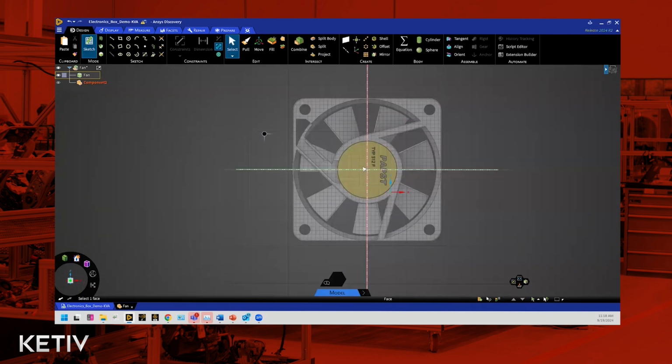This is to, again, simplify the fan geometry a little bit. You can see that there's a shroud around the fan, right? I'm thinking that maybe I'll just approximate the fan inlet face and apply a boundary condition on that. And maybe the shroud acts as a restriction, so I can just subtract it from the overall fluid domain as a solid body. As I perform the steps, this will be more clear.